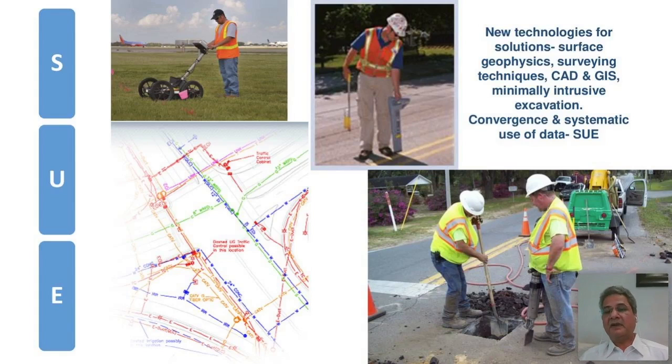I kept promoting it. In 2001, in fact, the Supreme Court came up with an order after the accident in Mumbai that for all trenchless projects GPR must be conducted before it. And then, after some time, I was the one who started educating clients that if you are depending only and only on GPR for mapping of utilities, the chances of success are just 40%. And in 60% cases you might meet with disappointment. Now that might come as a shocker to the people, 70% of you almost, who said that GPR is the best solution for that. All right, so we will go with this, that there are so many limitations of different techniques, and that's why I'm talking about this entire concept of SUE, the procedure.